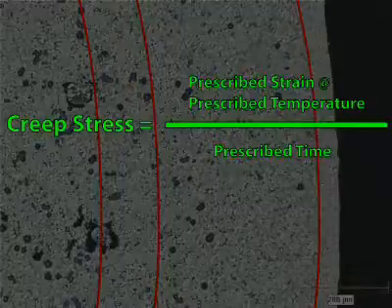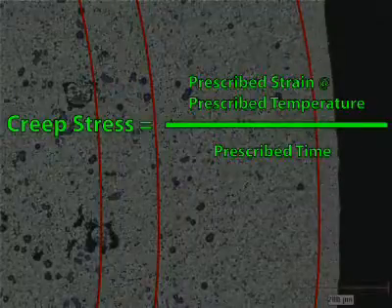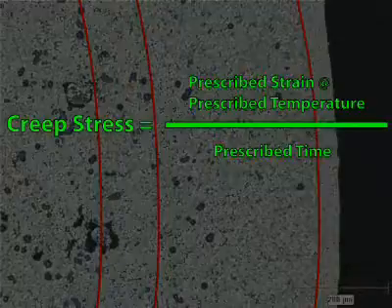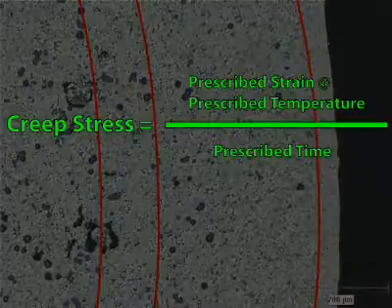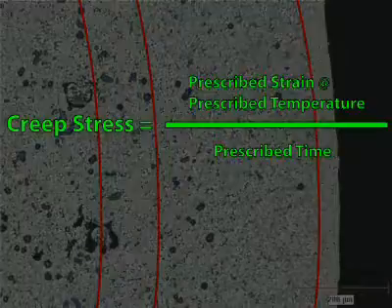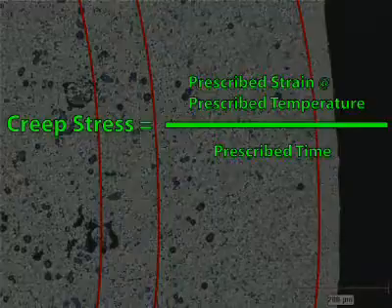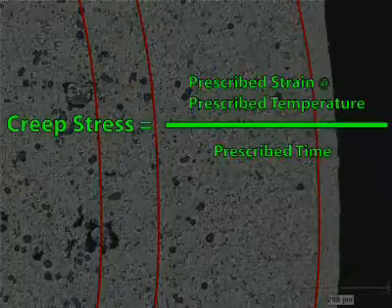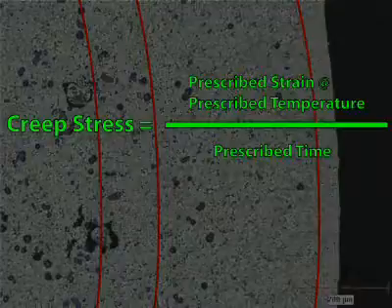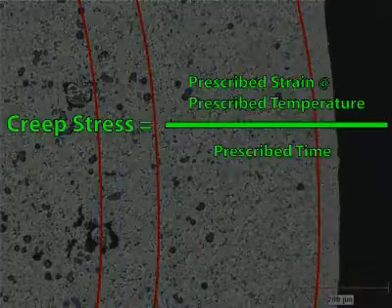The data generated are difficult to apply quantitatively in real-world applications because they are based on pure loads with no variation in load or temperature. The data are useful for eliminating some alloys from consideration and for comparing the relative merits of several alloys in a given application. See Figure 1, Stress versus Temperature, for 0.1% creep strain for a comparison of creep profiles at varying temperatures for the most common aluminum, magnesium, and zinc die casting alloys.